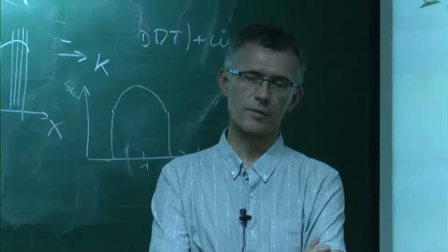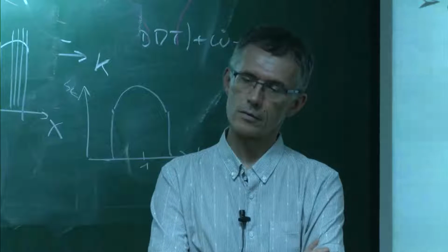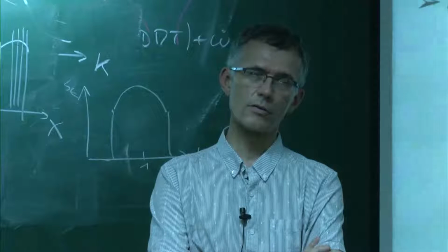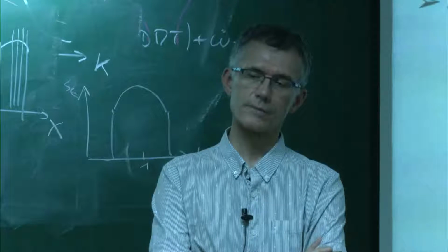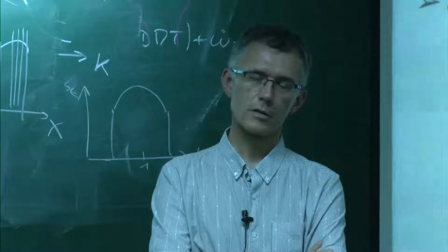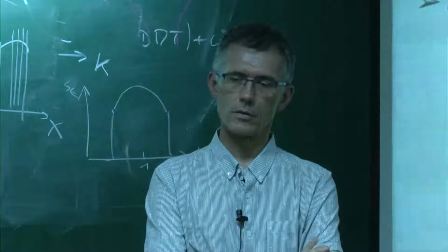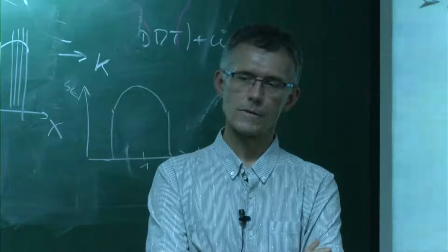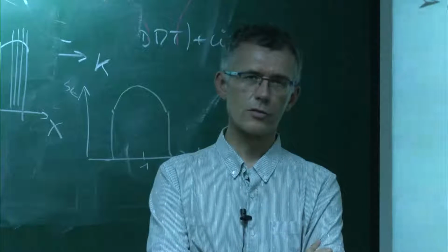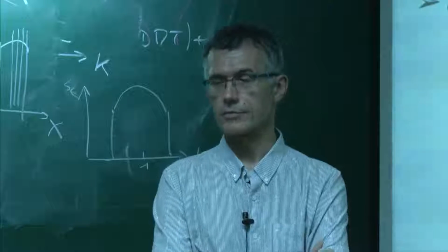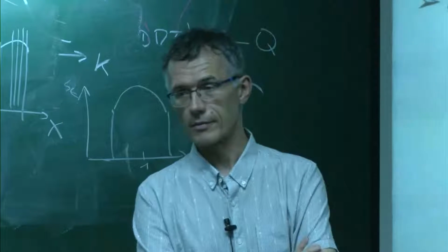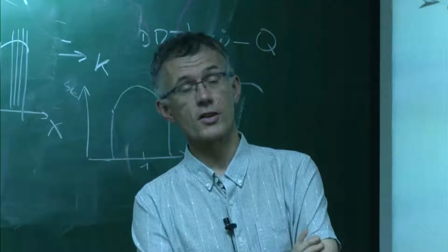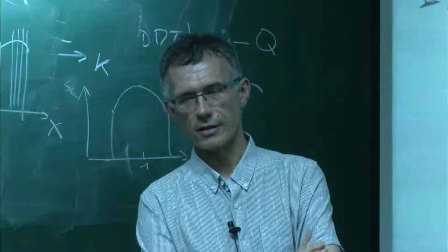We haven't tested it. In both regimes, right? Yeah, the linear eddy model should account for any type of flame at the subgrid level. Unlike the flame model you described, it would be applicable in both regimes. Yeah, LEM can normally do any regime, including chemistry. So that's a good aspect of it. Yeah, I did not describe all models. I mean, that would take forever.